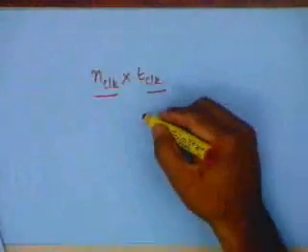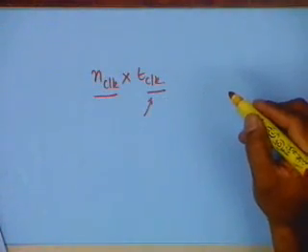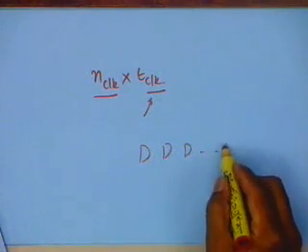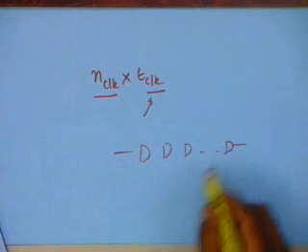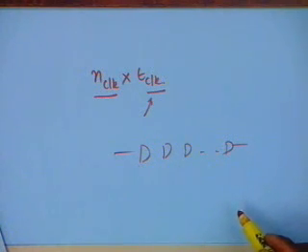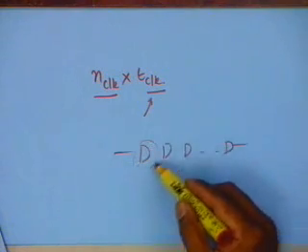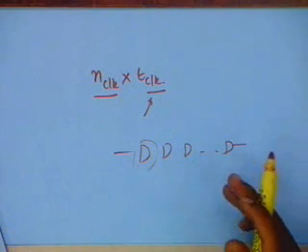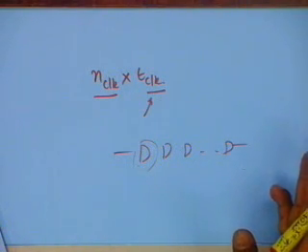My T clock is going to be governed by what my critical path is. If I have 10 levels of logic in the critical path, let us say for a simple case all 10 levels of logic are the same, then my delay is 10 gate delays for my clock cycle. My clock cycle should at least correspond to the 10 gate delays.